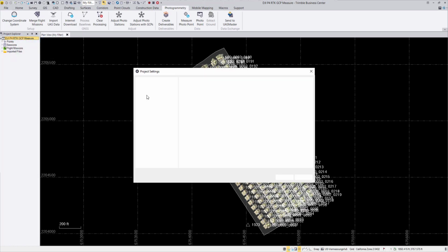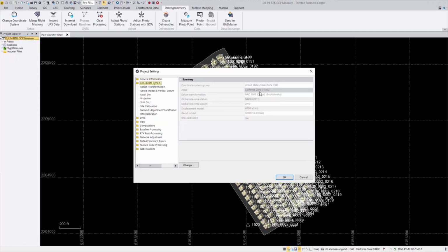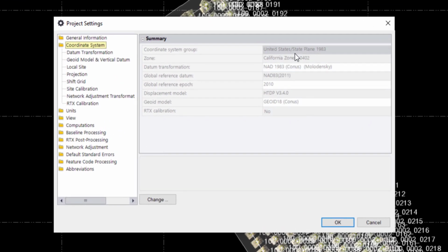So that means when we check here in the coordinate system itself, this needs to cover the correct coordinate system, as the coordinates will then of course be imported. And if your coordinate system does not include the GEOID, if it's without the GEOID defined, then of course this is wrong, because our ground control points use the GEOID18, and so you will have a height shift between your GNSS and your ground control points, because the drone images are imported and transferred into this coordinate system.